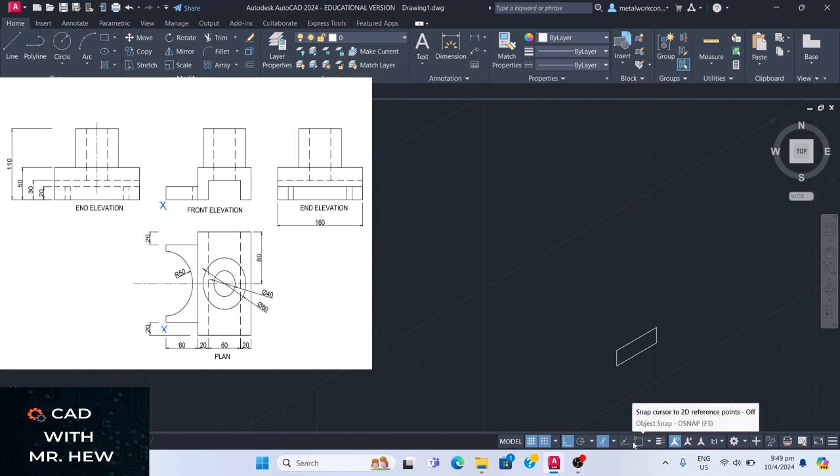we're gonna change our isoplane so that you can see the left side, right? So we're gonna go now, line, turn on object snap, which is this icon down here. It's fixed to there, that corner. And this will be the first point we click, and the length here will be 10 millimeters.